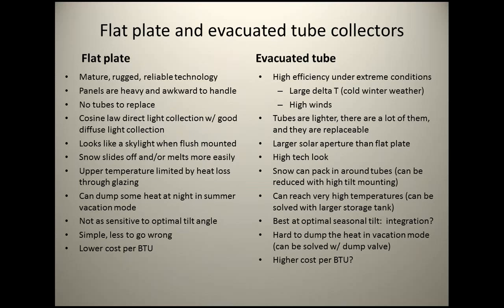The tube collector guys like tubes, and the flat collector guys like flat plates. Go to any of these places and they'll tell you about the advantages. So I'm going to run through it real quickly. The flat plate is a mature, rugged, reliable technology. It's been around a long, long time, and it's primarily made in the U.S. With the evacuated tube, you have high efficiency under extreme conditions: big temperature differences, high winds. Or if you want really hot water.